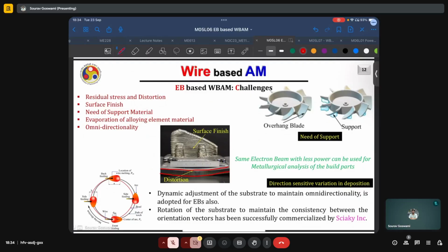And for residual stresses, as we will remember from our previous discussion, they are inevitable for any fusion-based process involving melting and solidification, because the metal tends to expand when it is liquefying, and upon solidification, it tends to contract. The presence of tensile residual stresses can be highly debilitating to the microstructure of a material, because no microstructure is perfect and there will always be some micro cracks, and tensile residual stresses can help in opening up these cracks and their further propagation.